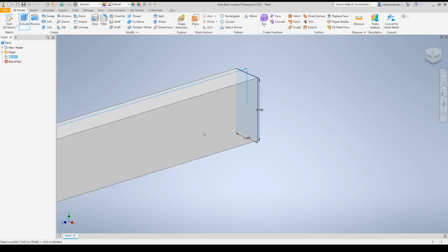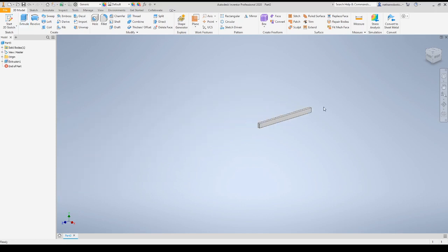That's about the right length for a drive rail, depending on the robot. Then we'll turn it into a tube, because right now it's just a solid bar, but we want a tube. So we're going to use the shell feature, which hollows the whole thing out. I could click OK now, and it would be a hollow body with a 0.1 inch wall all the way around.